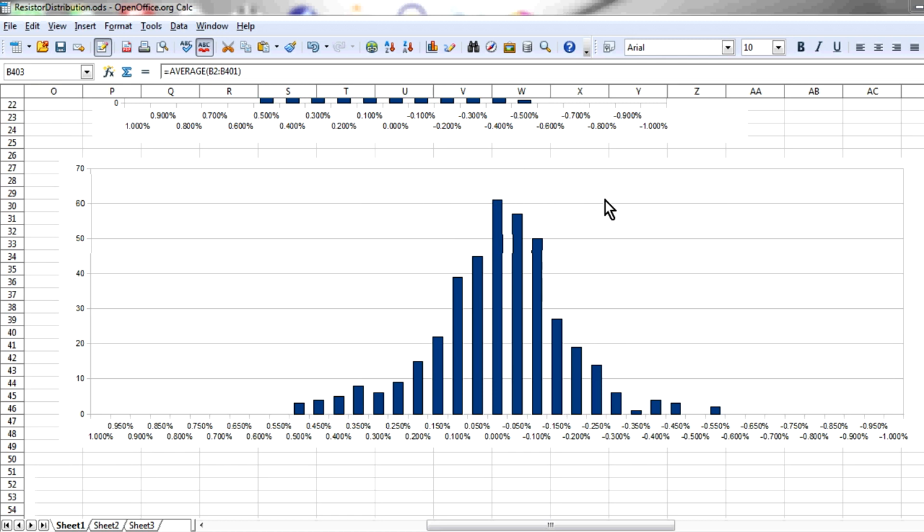And you might see the peak actually drift back and forth as you change various materials, suppliers, or change workers who are operating the machinery, perhaps, if it requires some sort of manual process or manual intervention. You can watch your processes drift, or if your temperature's changing in your manufacturing environment, that can alter things and all sorts of things. So you can get really good insights into manufacturing, whether components or products or whatever it is you're manufacturing, using this frequency analysis. It's a really good tool.